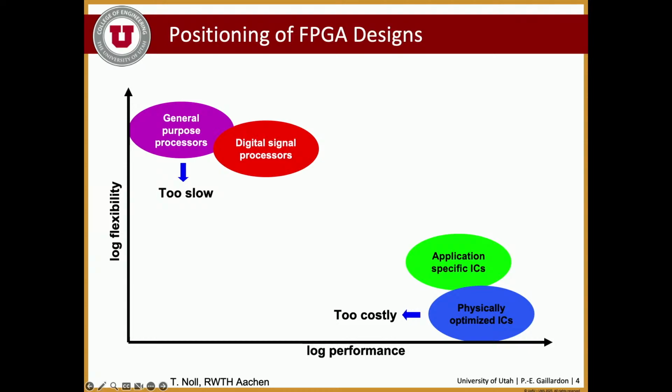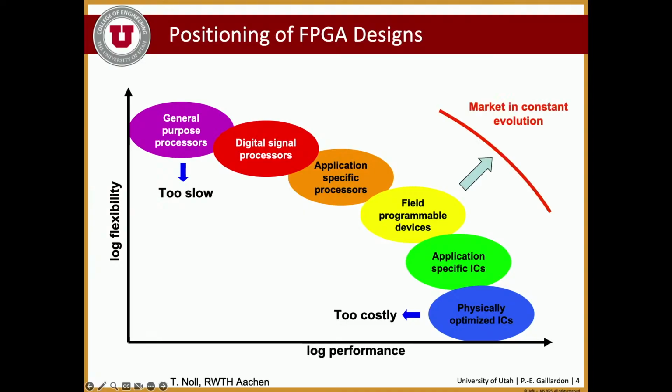Well, you have a vast array of options, right? Now, instead of having something fully wired, you can go one step higher and have something that can be programmed through registers and whatnot. Like that's typically a TPU type of topology. On that side, you'll have DSPs, right? So architectures dedicated to better performance while sacrificing a little bit of flexibility. So that's vector processing and whatnot. But if you just continue there, right, you'll find somewhere sitting right in the middle that concept of field-programmable gate arrays that will give you a decent trade-off between flexibility as well as performance.